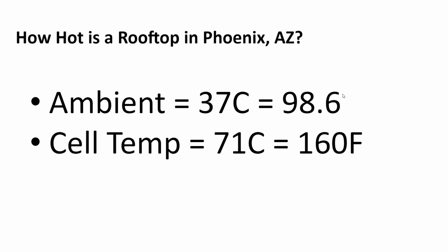And so I think it's useful to say, well, how hot does a rooftop actually get? What kind of temperatures am I exposing my system to? And that becomes an electrical design issue because different conductors and different pieces of equipment have different temperature ratings. And so if you're looking for a temperature rated terminal box to put on the rooftop, you might not find it at your local electrical supply house. So how hot does it get in Phoenix, Arizona? Well, it gets up to 160 degrees Fahrenheit on the roof.